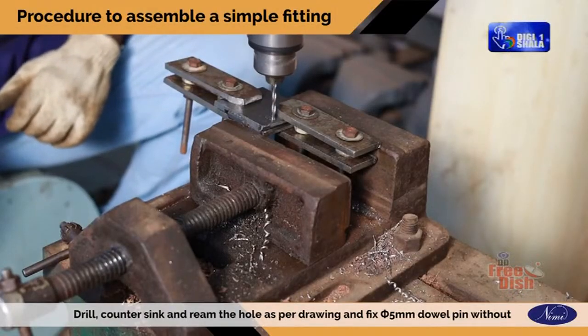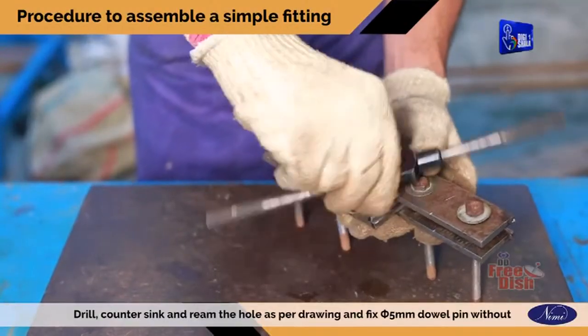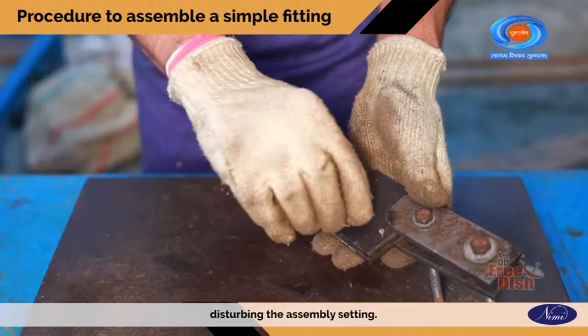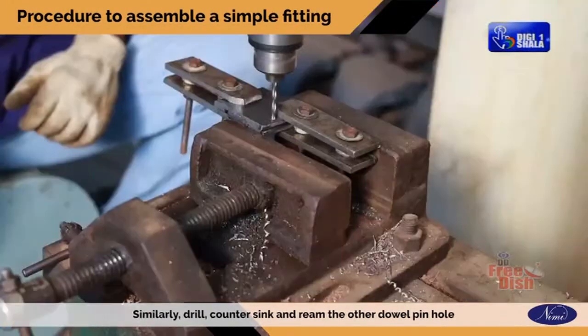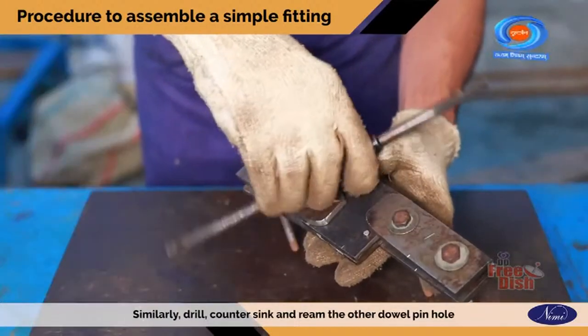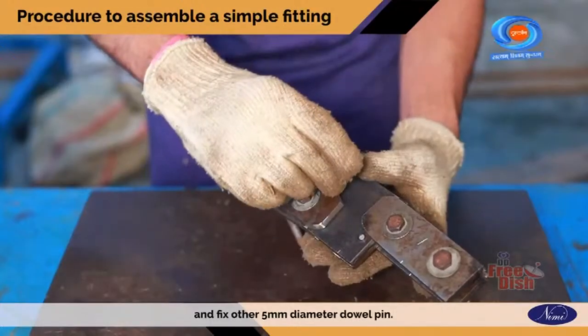Drill, countersink and ream the hole as per drawing and fix diameter 5 mm dowel pin without disturbing the assembly setting. Similarly, drill, countersink and ream the other dowel pin hole without disturbing the assembly setting and fix other 5 mm diameter dowel pin.